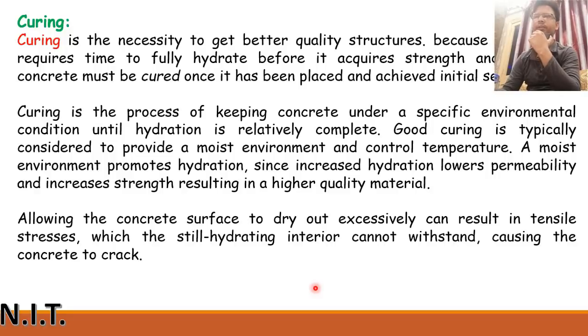There are different types of curing available. We will study all those curings in the next course, but over here I'm just giving you the overview. Curing is necessary to get better quality structures because the cement requires time to fully hydrate before it acquires strength and hardness.